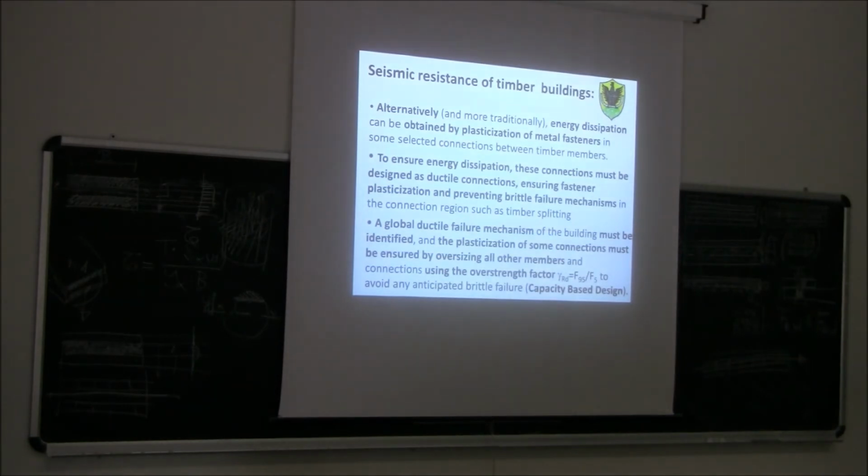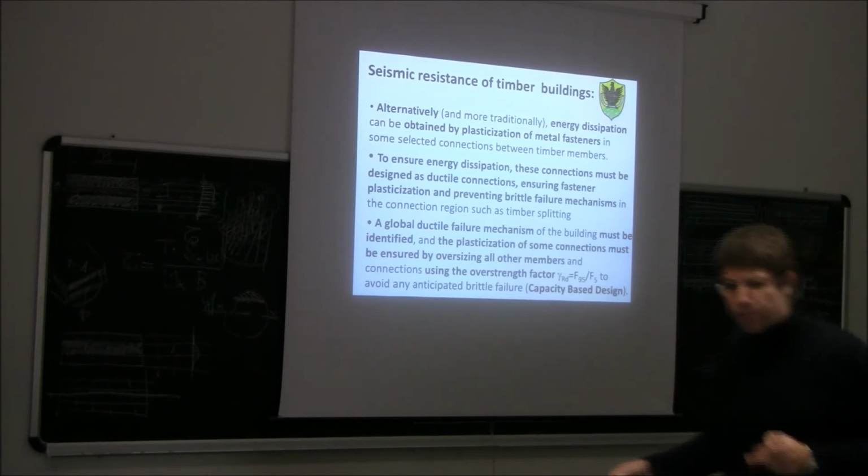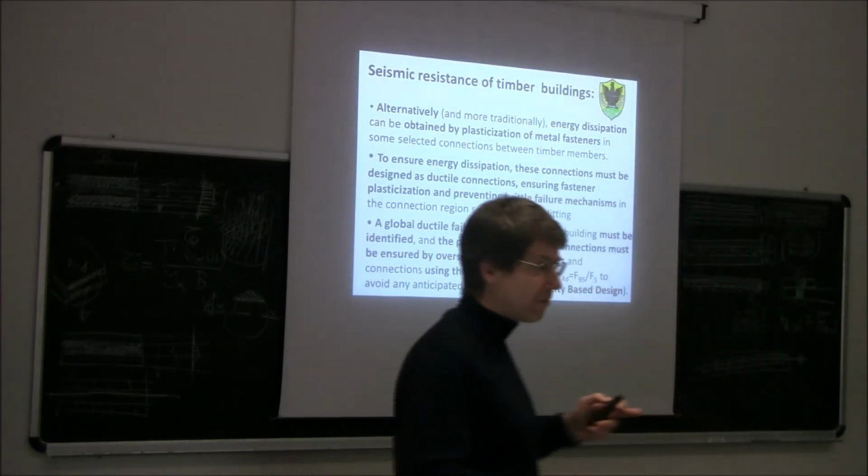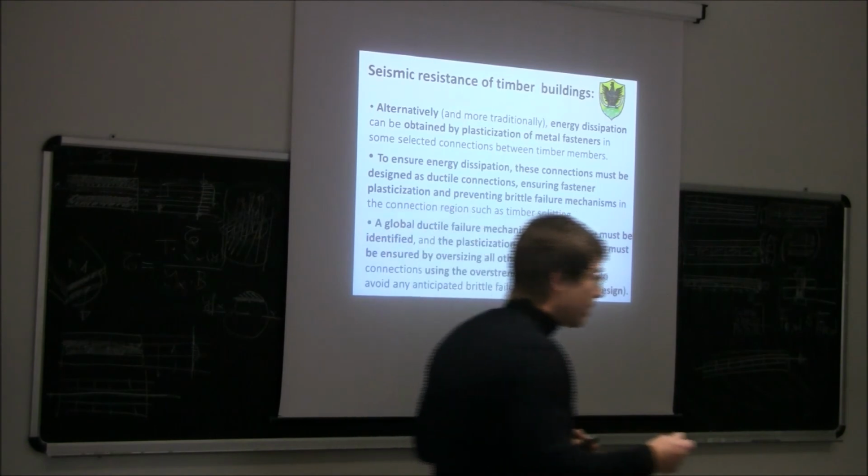Now, going back to your design, the one you did for reinforced concrete, can you remind me how you did your design? So, you started from a frame, then you chose one ductility class, for example, high or medium. Then you calculated the behavior factor, you calculated the elastic forces, and then for those elastic forces, you designed the members. For example, for the beam, did you design the beam for the stresses coming from the reduced elastic forces, and for which kind of verification?